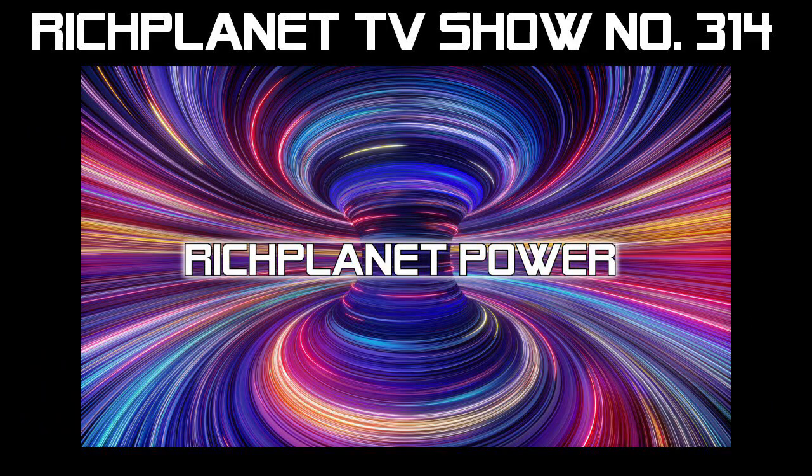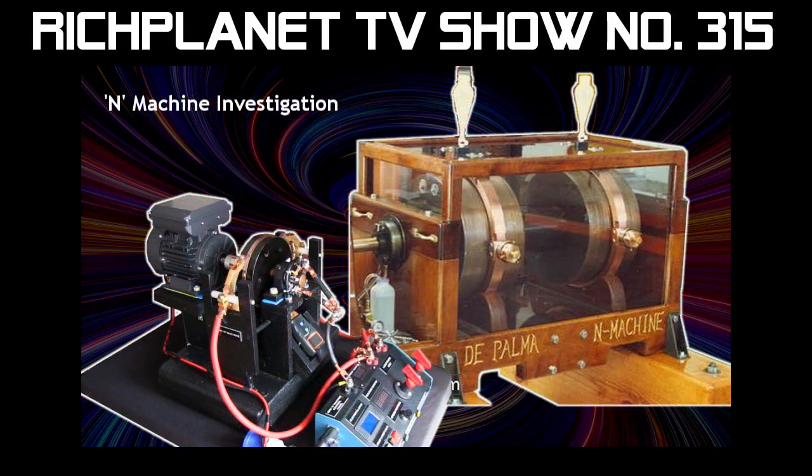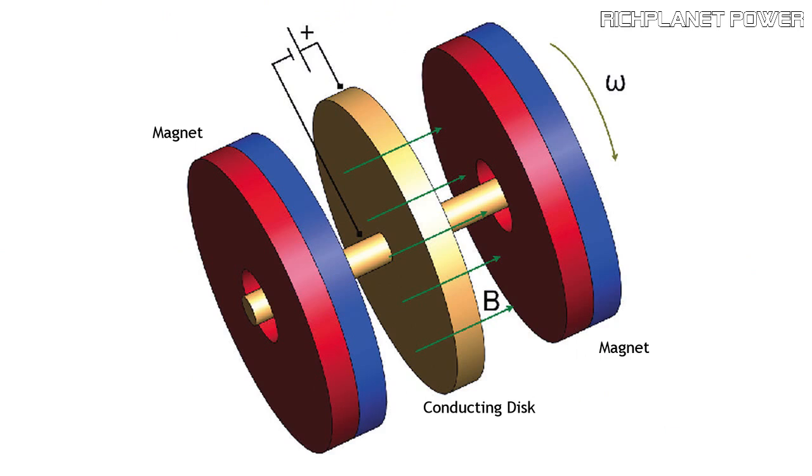Now, in order to understand what an N machine is and to see a detailed description of the experimental machine that I built, please watch show numbers 314 and 315 before watching this. An N machine is the name given by Bruce De Palma back in the 1980s for a particular type of homopolar generator. A homopolar generator consists of an electrically conducting disc which is spun at high speed inside a magnetic field, resulting in a DC voltage being produced between the rim of the disc and the center of the disc. Electrical power can then be drawn off from the rim and the center using brushes.